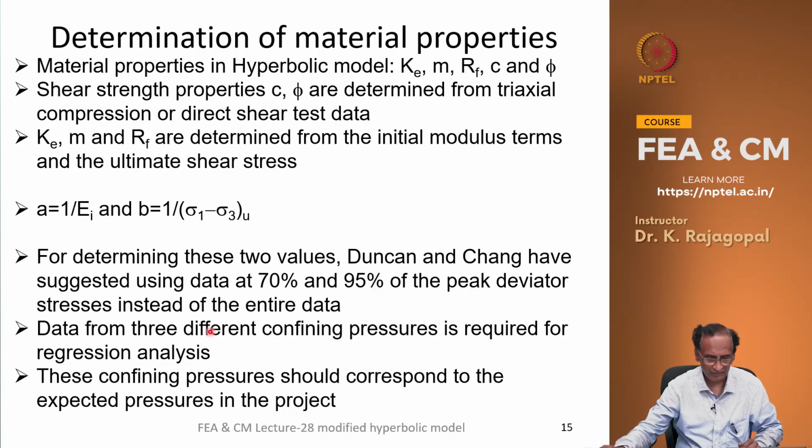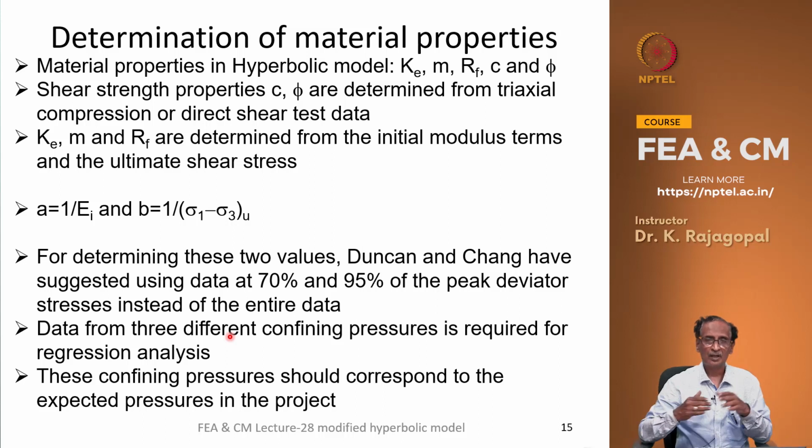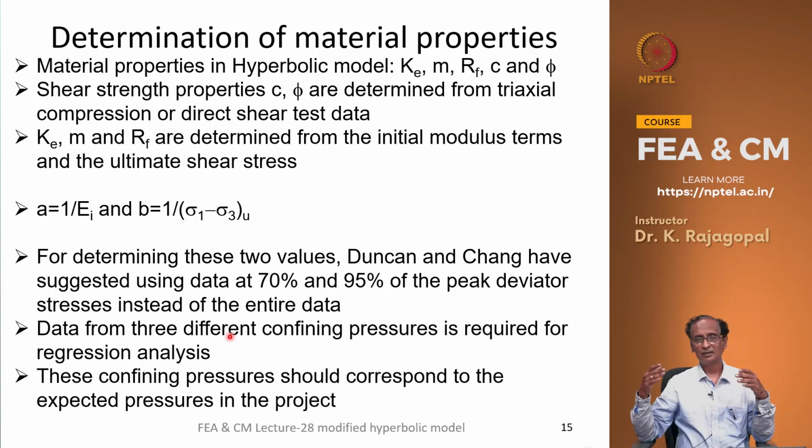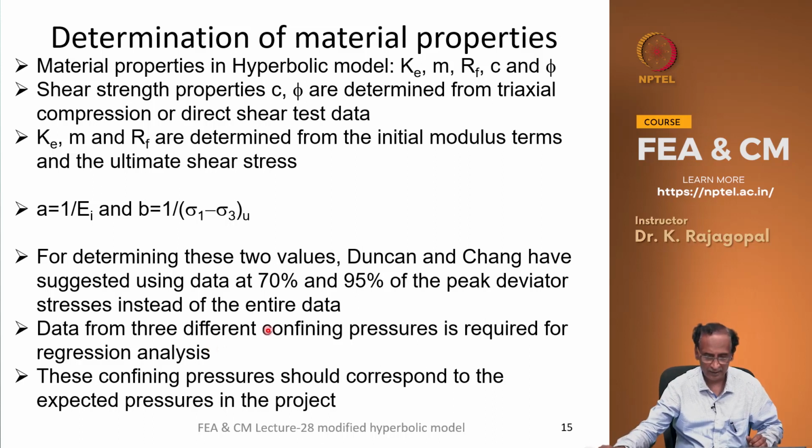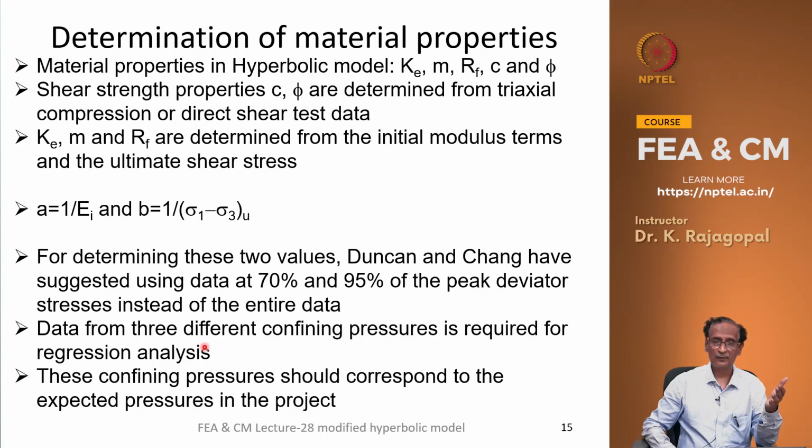And for determining the model parameters, we need to perform the triaxial compression tests at different confining pressures, and the range of these confining pressures should correspond to what we expect in the field.